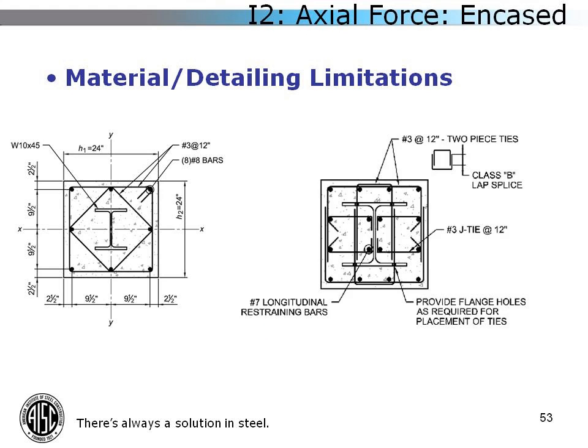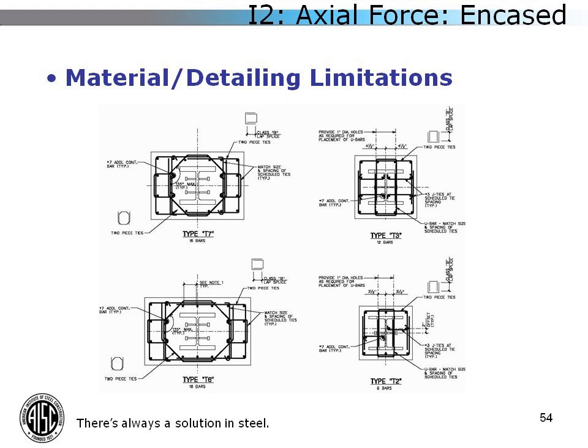You can do a third thing as well, and that is to use 2-piece U-ties. This diagram is actually showing holes drilled within the structural steel member to put these U-ties in. From personal experience, that is not a good idea. Contractors do not like to do that, but it's an option if you absolutely have to do something. And then you get into some messy situations as shown here.